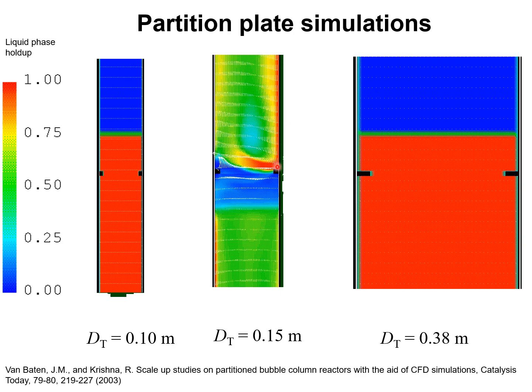Indeed, there are nooks and crannies created due to the introduction of the sieve plates. Indeed, you see here a large region which is red in color, indicating pure liquid, and this would lead to perhaps coking and clogging of the sieve plates.